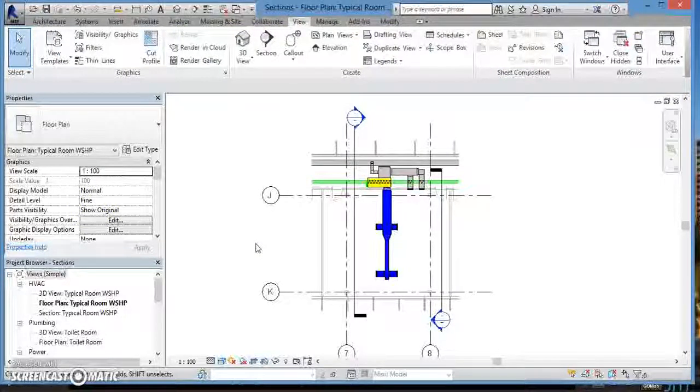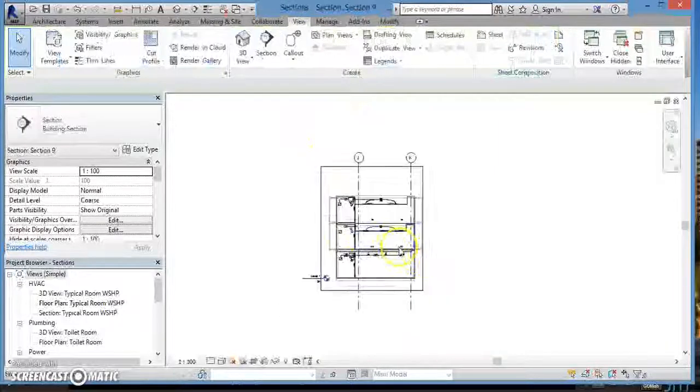So far, we've only dealt with how to create and edit the section view. But if you want to actually look through the section view, you have two options. The first method involves going to the project browser and opening up the Sections section from there. The other method, which is arguably simpler, involves simply double-clicking on your section line within the arrow that shows the direction the section looks out at. Then you will be taken directly to your section.